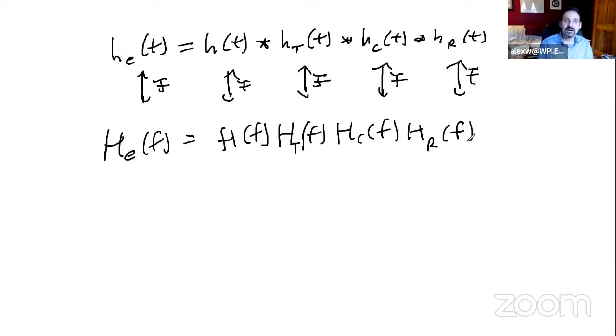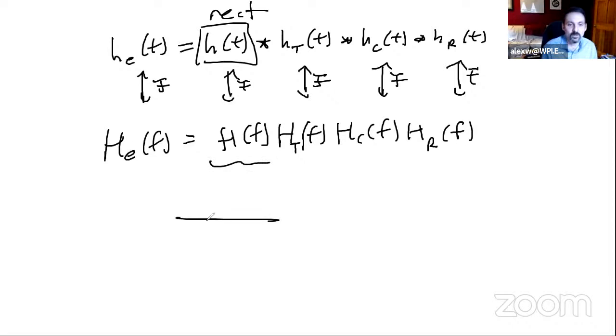Just between you and me, I would much prefer to do a product of a lot of frequency responses rather than the convolution of a bunch of time responses, okay? So that's super important because this allows us to more quickly realize implementations that otherwise would be very challenging. But heads up, if this was a rectangular response, this is going to be that very annoying sinc response, right? Okay, so very important. Nevertheless, something to keep in mind when we are actually building these things.